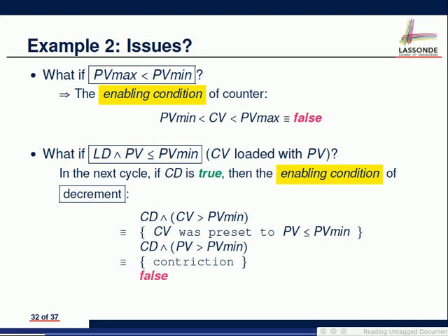That's another thing they should have made clear. It is possible to set the PV to a value such that you will never be able to decrement the value of the counter anymore. It's possible. But is that really what you intend or not? Maybe yes, maybe no, but it should be made clear so we can discuss. Okay, finally, these are the two example issues I want to show you. Finally, I want to show you what we can do to make things very clear for communication.